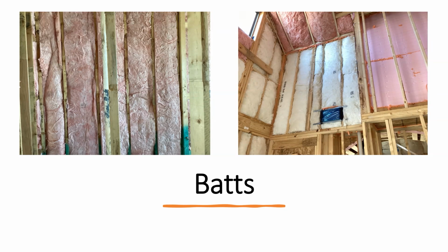We talked about it before, though. In the energy model, you can't really do it by component. I mean, you can do it by component, meaning the floors, grade 1 or grade 2. But if you have a section of wall that is not meeting grade 1, you can't just say, well, 100 feet of the south facing wall is grade 2 where the rest are grade 1. You have to do an overall. Well, if it's not quite enough square footage that's poorly installed, is it going to be detrimental to the overall grading of the house? So that's what you have to determine.